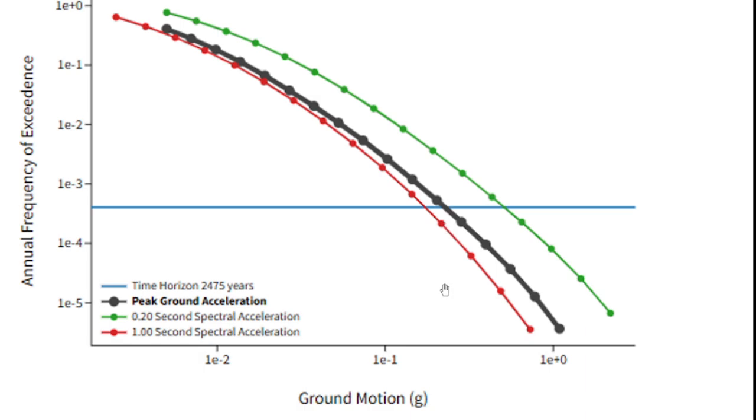If you extend this down vertically, I obtain the corresponding peak ground acceleration. For example, you can see that here it is approximately, say, 2.04 g, though I have not clearly marked it out. In a similar way, you can also obtain the spectral accelerations corresponding to the short period of 0.2 as well as 1 second from these hazard curves.